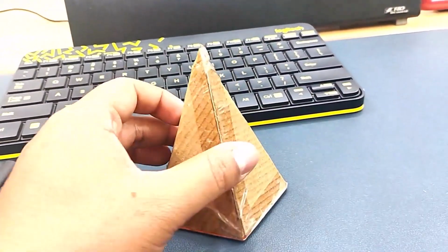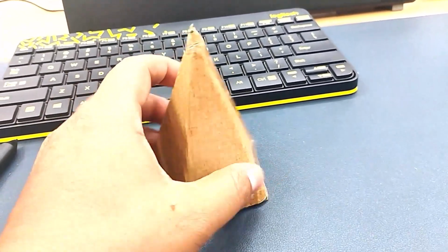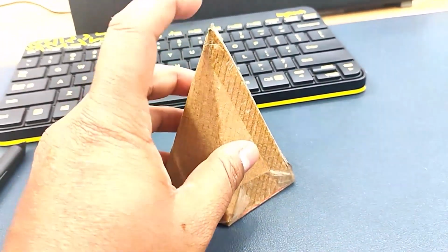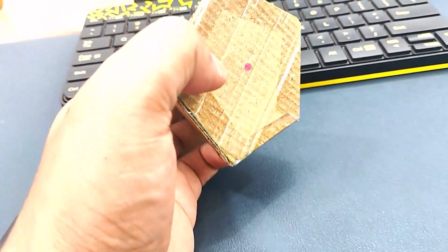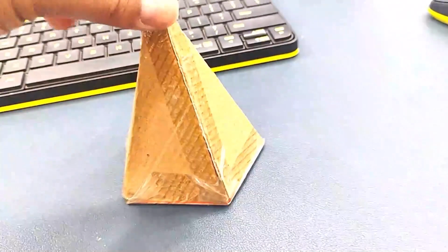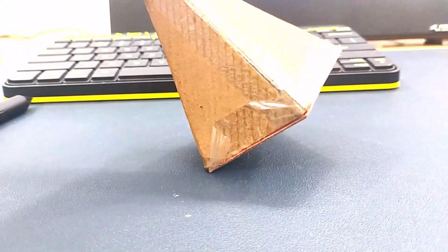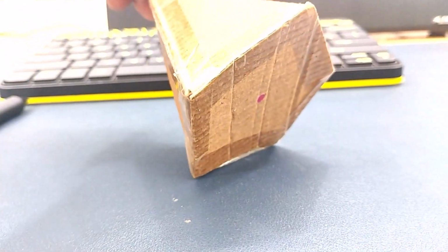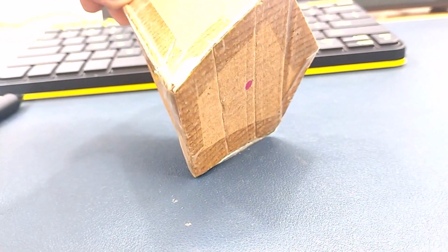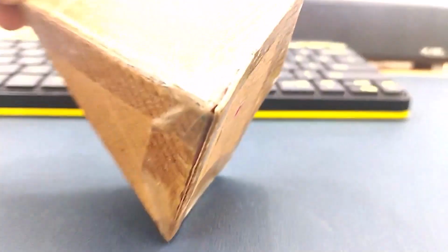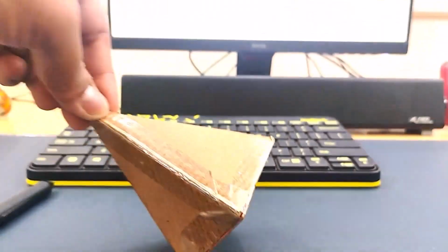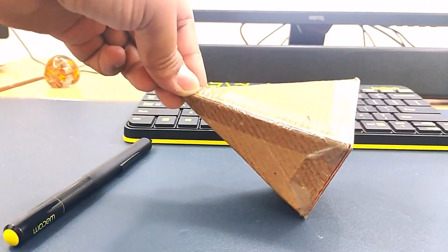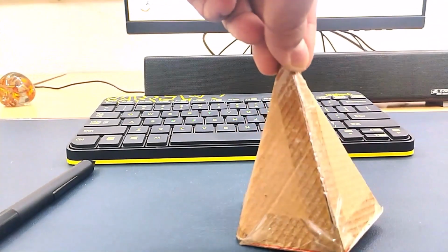This is a pentagonal pyramid. So where is the axis? From here until you reach here. That's the axis. Now it has been kept like this. As you can see, one base edge is in contact with the horizontal plane always, and simultaneously the axis is making some angle with HP, right? So this happens in your step number 2. This is for your step number 2. This is going to be your step number 1.